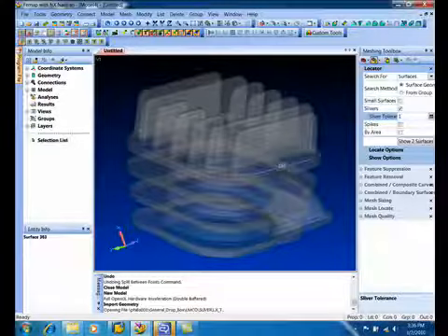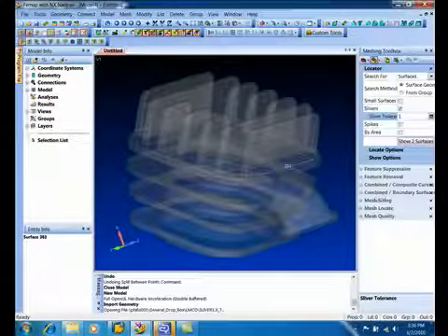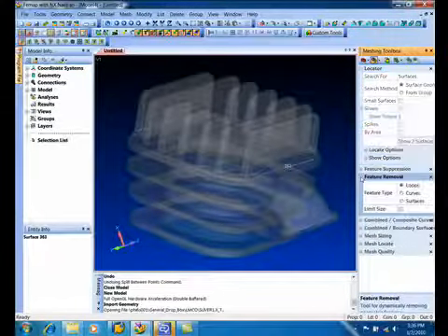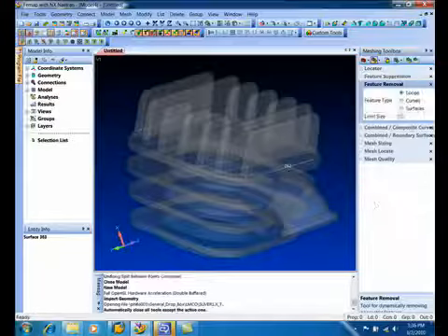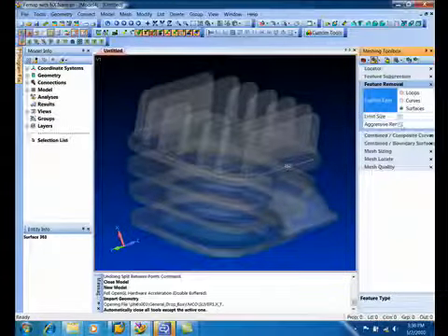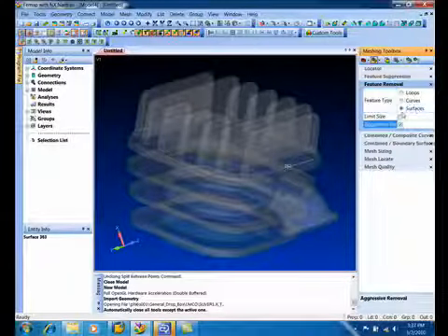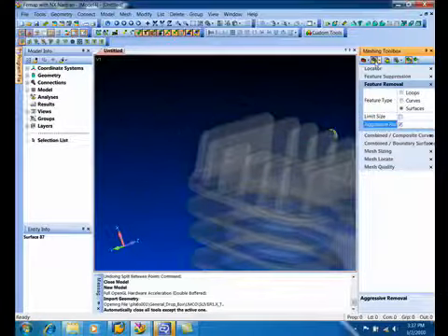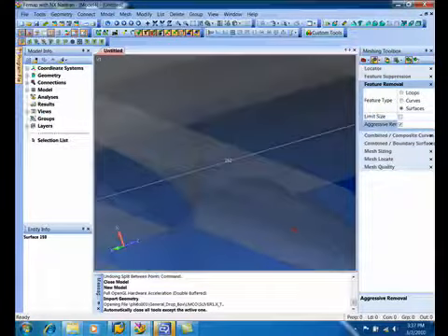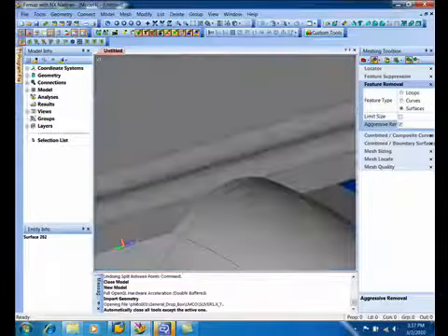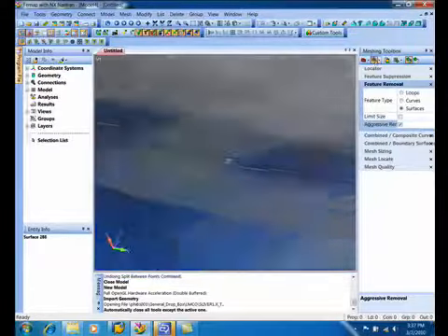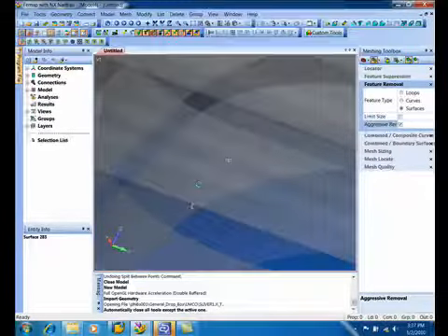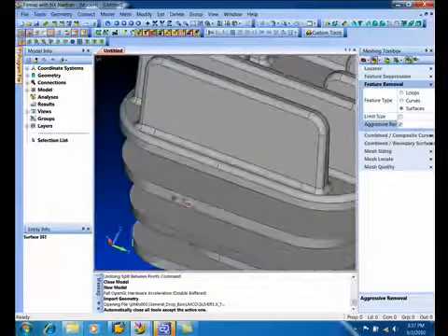The first thing we'll do here is get rid of them permanently by cleaning up the Parasolid geometry. So we're going to go into feature removal. I'm going to say surfaces, and this is just removing regular fillets and chamfers and things. We're actually going to aggressively squish this right out of the model. So I'm going to look at the first one, second one, zoom in here, and just go pick them. And it's going to get pulled out of the model. Go find the other one, pick it, and let's see what else we've got here.